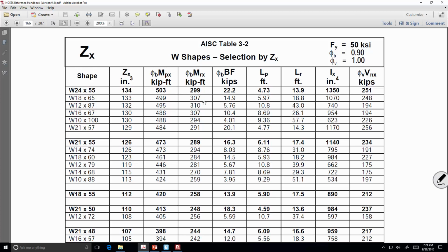We can write that down, although ultimately we won't need it. I'm going to use the board right here, but I'll copy this down here in a second. So let's write down some other values. Let's see. I've got phi MP, which, if you haven't had steel, that is the absolute maximum capacity of a beam. A beam cannot exceed MP, and that is 503 foot kips.